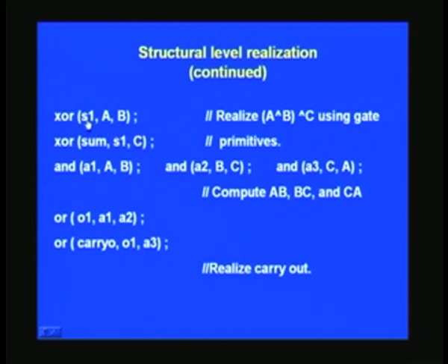So here what you see are the intermediate signals, and this is to invoke a primitive which is available in the libraries of Verilog. This is exclusive OR, which you are already familiar with, and similarly this is AND and OR, and the first one stands for the output of that gate, whereas the rest will be the inputs. As I mentioned, they are all normally restricted to 2 inputs, and some offer higher inputs as well, but that's not guaranteed on all the platforms. And finally you plug this into the next exclusive OR along with the third signal which you have not used earlier, to get the final sum output here.